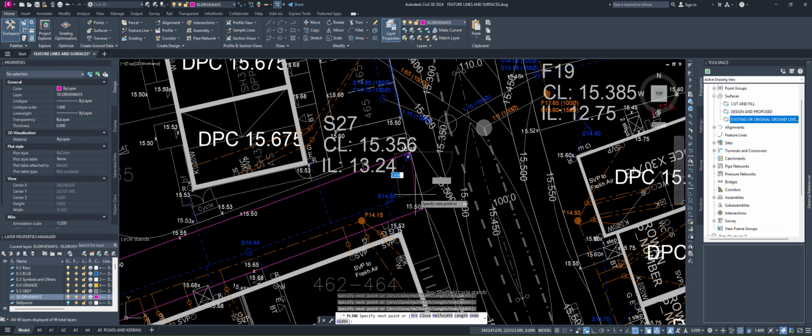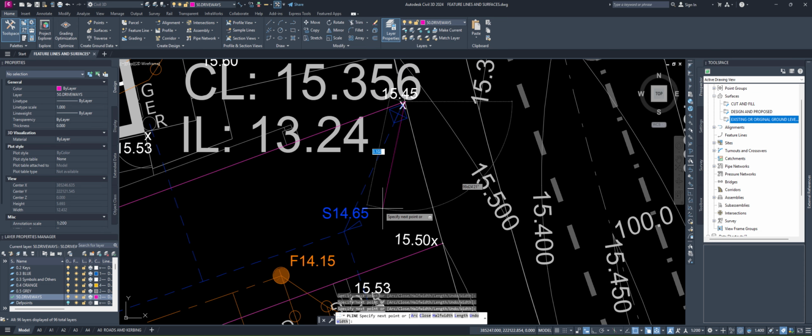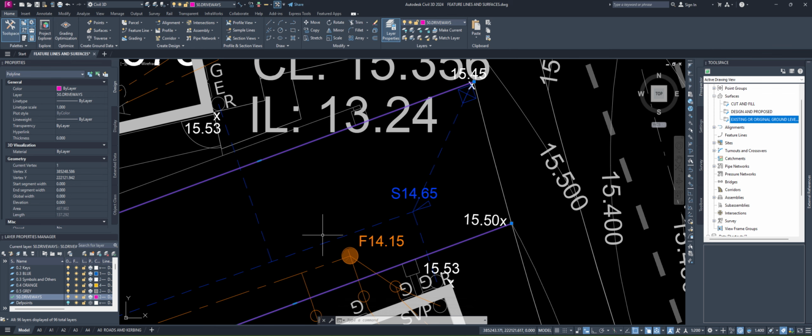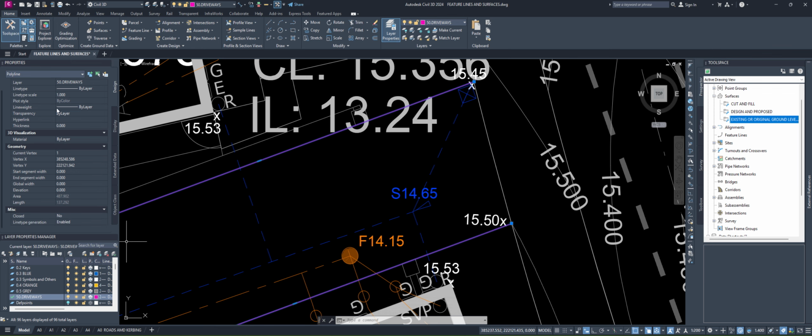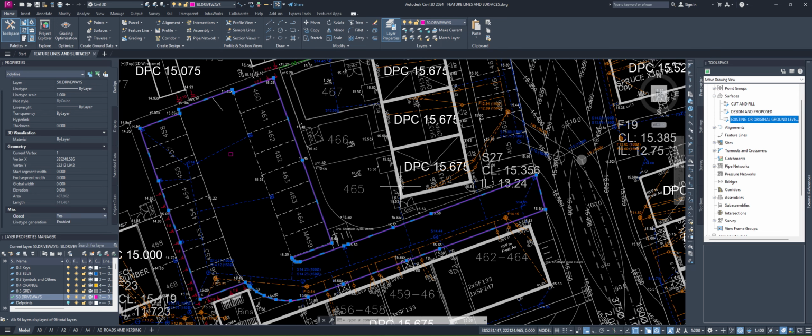All we need to do is close that line work. I'm going to press enter so I can escape from my initial polyline command. Then I'm going to select my polyline by itself and scroll down in the properties tab until I see Misc. Under Close I can click Yes, and that is going to automatically close and loop my whole model. This way I'm sure there are no gaps left.